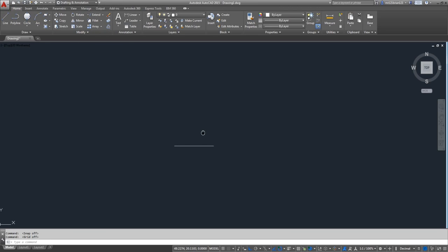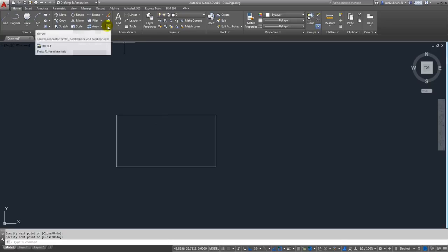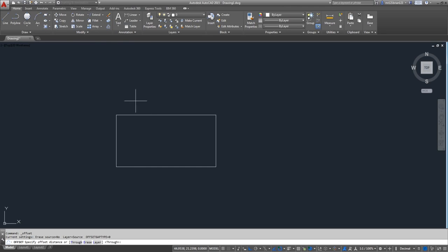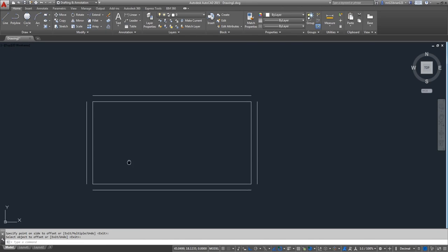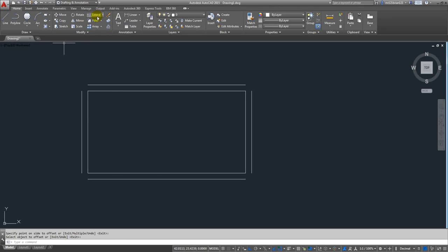Okay, I'm making the living room. What we are going to do is a line of 4, and then a line of 8, and then a closing line right over there. Another command that is very useful is called offset. When you press offset, it's going to make a copy of the line you're selecting to whatever place you want. For example, I want to select this line to point 3. Then I select the line, I move to the place I want, for example at the top, this one to the right, this one down over here, and this one here, and there I'm starting to have a top floor plan, and I'm going to use the fillet to close this, and close this, and close here, also here.